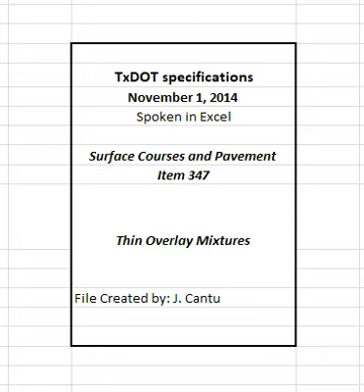4.5.1 Storage and heating of materials. Do not heat the asphalt binder above the temperatures specified in Item 300, Asphalts, Oils, and Emulsions, or outside the manufacturer's recommended values. Provide the engineer with daily records of asphalt binder and hot mix asphalt discharge temperatures, in legible and discernible increments, in accordance with Item 320, Equipment for Asphalt Concrete Pavement, unless otherwise directed.